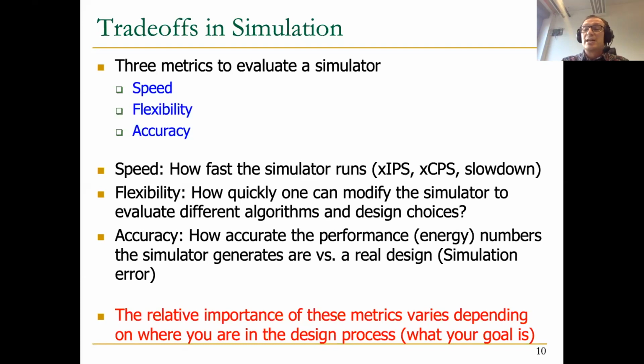For every single thing that's happening in the pipeline, it will launch a new thread. And these threads need to synchronize somehow. And if you got the synchronization wrong, basically your results would be completely wrong. Not only just timing results, but actual functional results would be wrong. So the simulator would actually be giving an error many times when people modified the code. Why? Because they made a mistake in terms of thread synchronization. And the simulator would barf, meaning it would stop saying that, oh, functionally, I've executed something wrong. Well, why? Because somebody didn't synchronize things accurately. Okay?